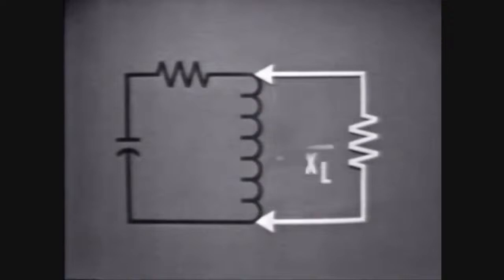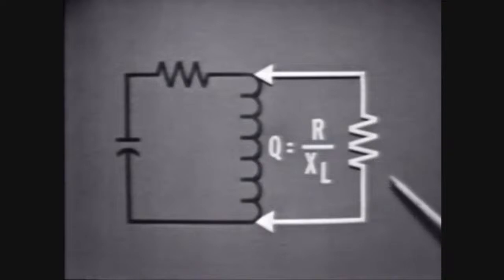However, there is another quality factor that concerns external circuit resistance, and in this case, the resistance should be high. In other words, the amplifier connected to the frequency determining device should offer maximum impedance to the tank. Even then, there'll be some energy loss to the external load, which must be regained by increasing the feedback.